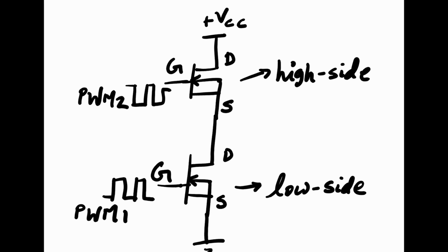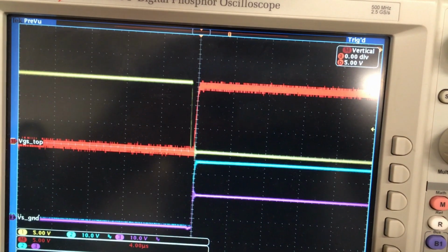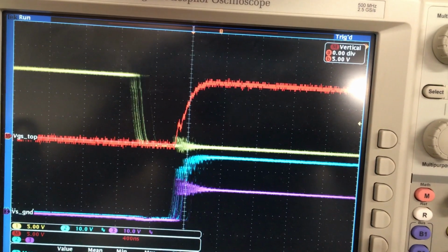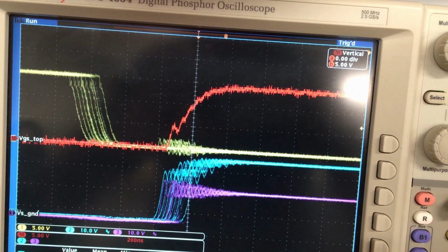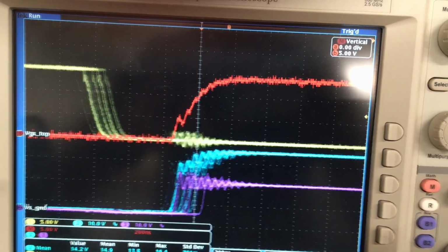To drive a high side switch correctly, we need to contend with the fact that the source terminal would be floating between the ground and the power supply based on whether the top switch is on or off. This is where a gate driver becomes handy due to its ability to level shift the driving voltages with the power converter switching states. Okay, enough with the theory.